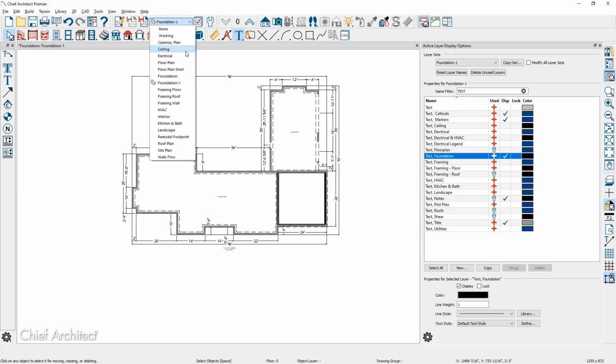I've got an electric plan view. I've got one specifically for landscape, specifically for remodeling. They can save you a lot of time. It might take you a little bit of effort to set it up. Once you get it set up, save it in your template plan, and then you will have that for all of your future plans as you move forward in your design process.